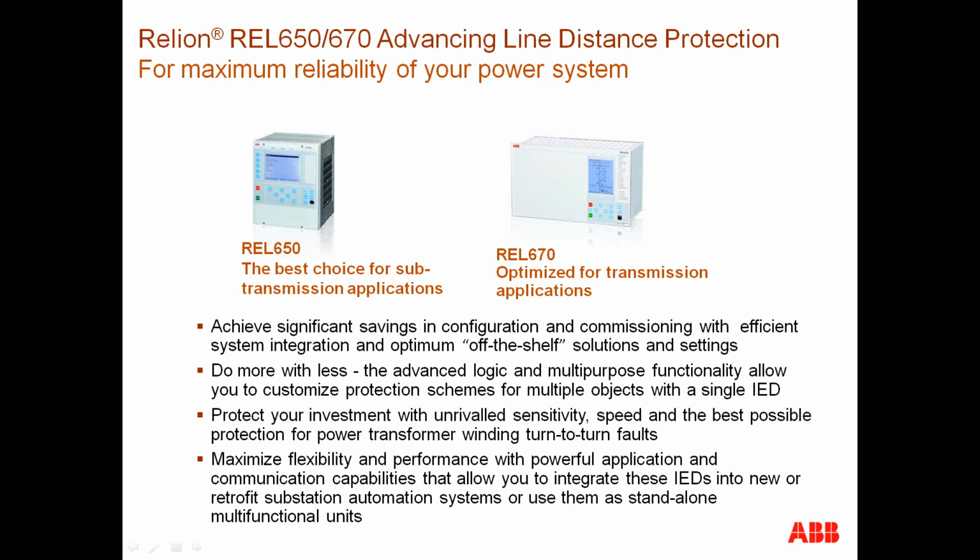All right, then, is it a good idea to use a distance relay to protect a series compensated line? Well, it can be done. I would always say that any line that requires communication assistance, I would go ahead and use phase segregated current differential.